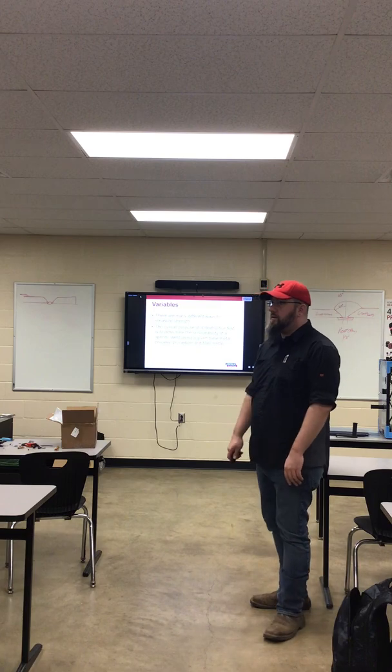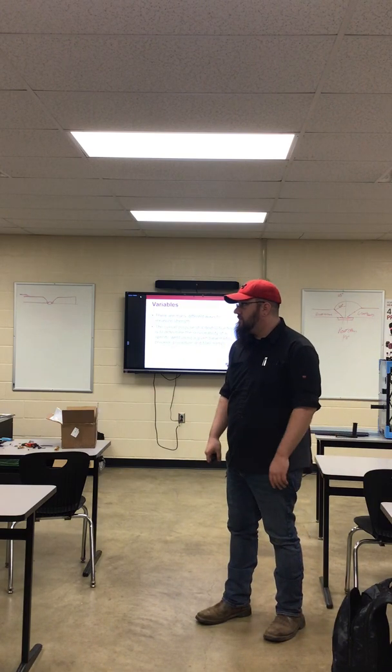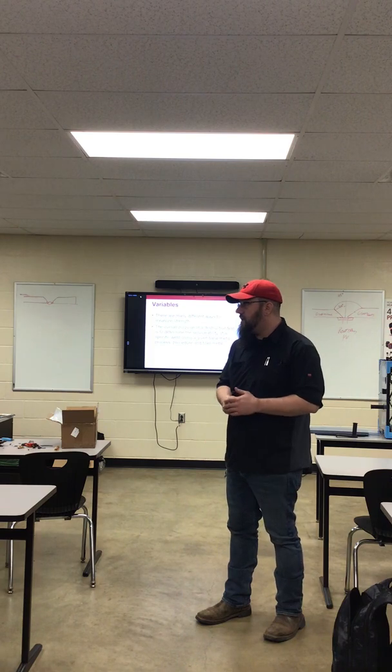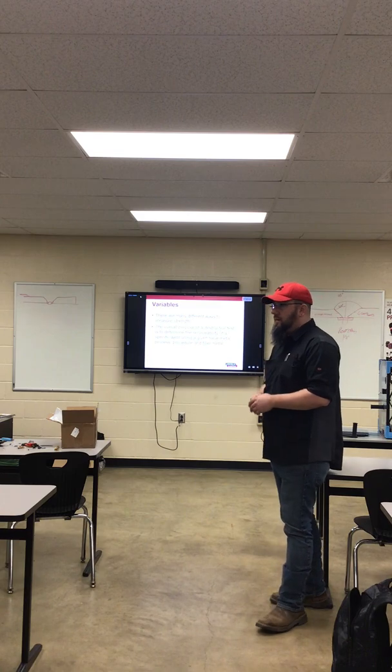Well, what about temperature, moisture content? Our 7018 electrode, is that susceptible to moisture damage? Yes. Absolutely. Is that going to affect our weld quality? Yes. Absolutely.